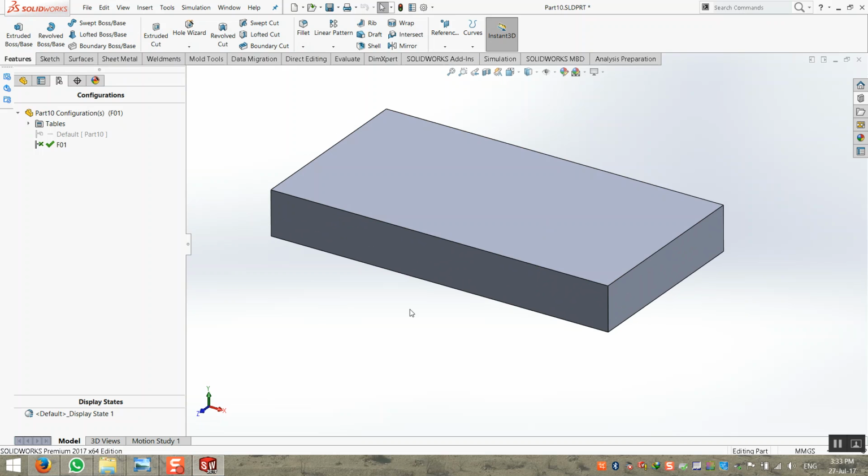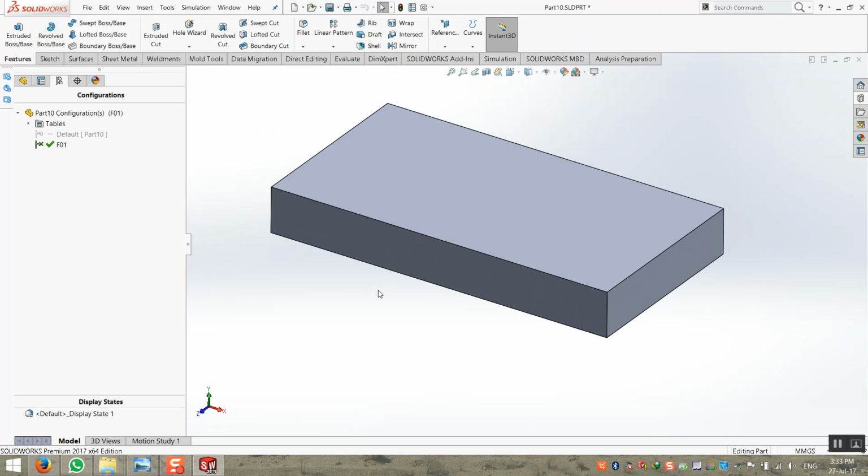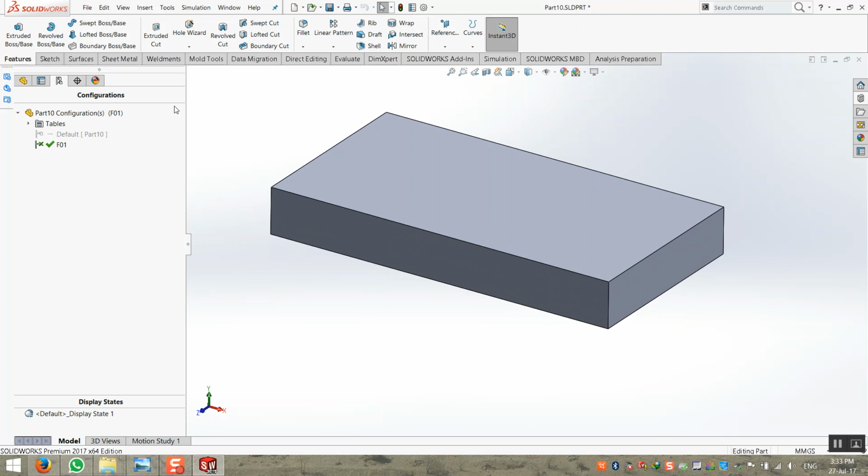But I think it's advisable to make an export from Solidworks and have some numbers. But you don't need to retype all these things. Yeah. It's better to make an export from the Solidworks. Yeah, true. Then you can type only the numbers. Using freely, no load, no memory load, no hanging, no something like that. But it's very important to know the names of the dimensions that you use. Very important. Okay?